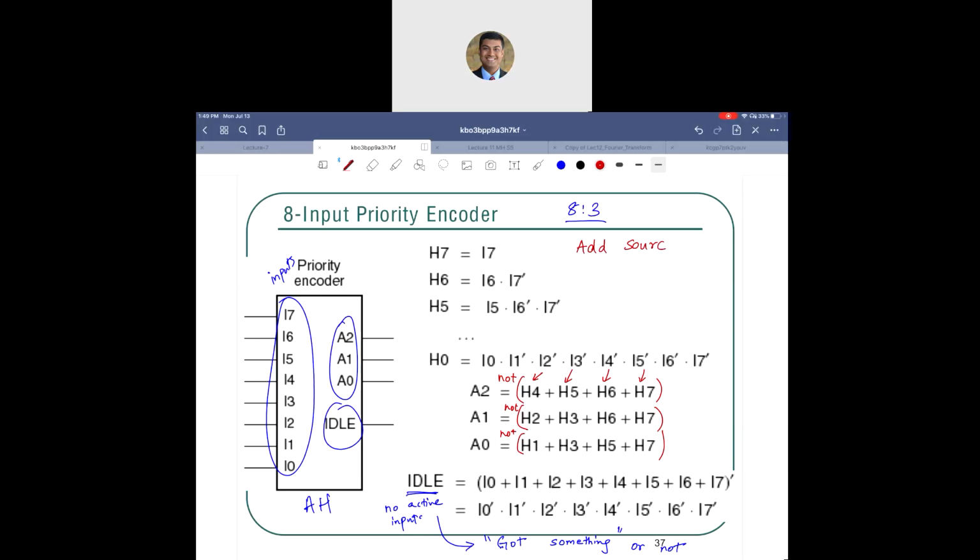there is an add sources option, and there is an add design sources option, and there's also an add constraints option. So for example, if you are working on task 1, you create a new design and a new constraints, work on that, and then when you are ready to move on to the next, you right click on those VHDL and XDC files and select remove from project, and then add new design sources for task 2, and so on. And when you go to check off, remove certain design sources and bring in the new ones for that task. By right clicking on the VHDL file or the design file, you can also disable them when checking others. That should also work.